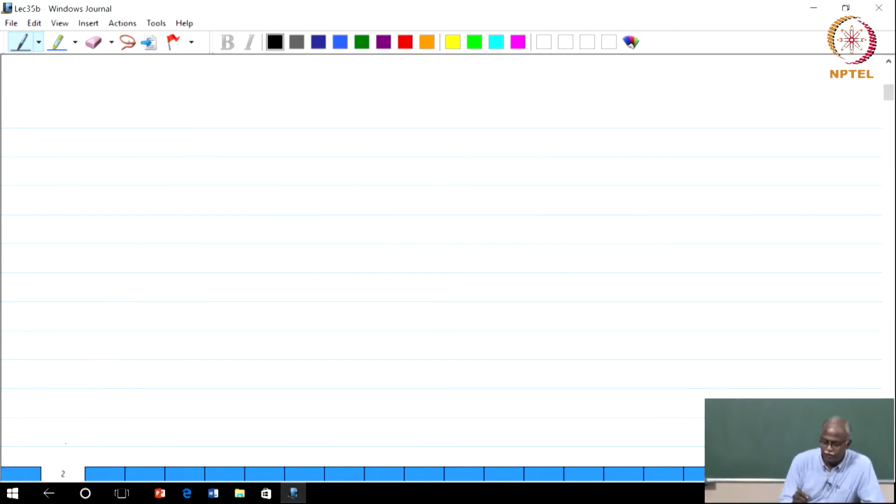fact that we want to deal with wideband signals. So that is primarily our interest. A wideband signal has several challenges. You get frequency selective fading, and the complexity of the equalizer is quite a challenge. So we said that a wideband signal we will treat as N narrowband carriers, N cross B. Okay. So this is where the multi-carrier modulation concept is coming from.